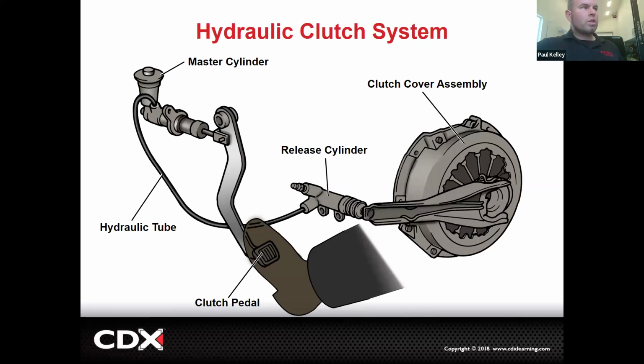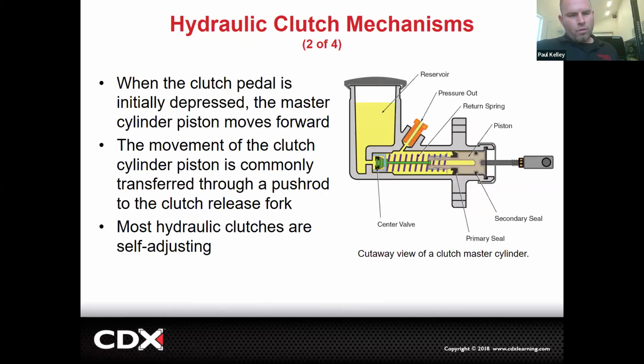And then just remember, we have to check the fluid level right here. Sometimes it's kind of cool, but sometimes they'll tie it into the brake master cylinder reservoir, because they both use brake fluid, so that's kind of nice because you have access to more of a reservoir. These reservoirs are pretty small. If it's a standalone master cylinder reservoir, they're tiny. So we got to make sure we check that fluid, but don't overfill it.